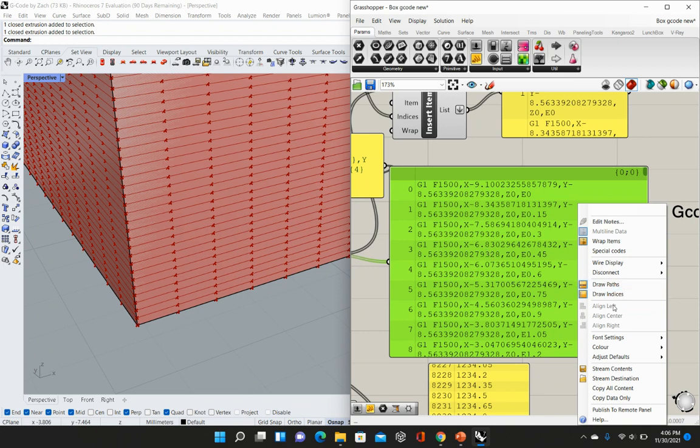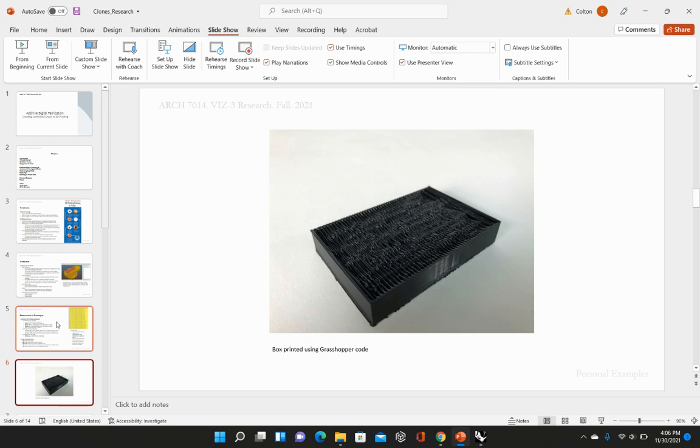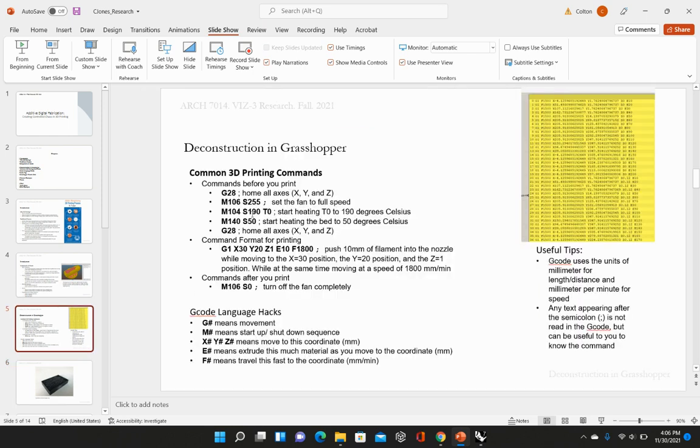Now, also, when you do this, you can copy and paste into your text document. You also need to bring back all these M factors. So you can literally just copy and paste all of these right at the beginning of your text document, and then this one right at the end of the text document, and then you want to save it all as G-code.